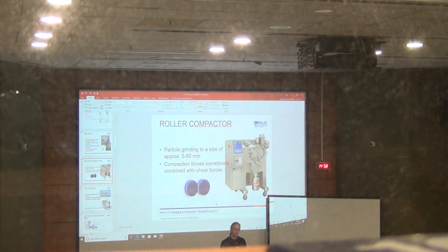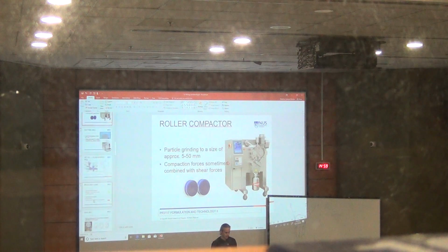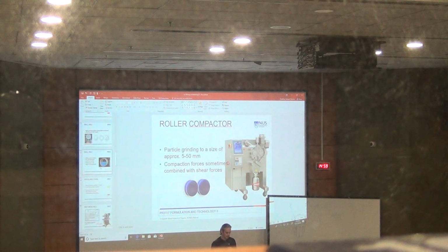So this is the point that is important, I think, when we are talking about milling. You have one principle which is somehow embedded in each particular milling type: cutting mill, for example, ball mill, for example. The jet mill is mostly working on the basis of attrition and impact, but it also has a certain principle here. It only uses the particles to grind themselves. There's never really impact on the surface of the mill, which means you have a much lower influx of impurities here. This is a thing that I mostly wanted you to see when going through the different mill types.